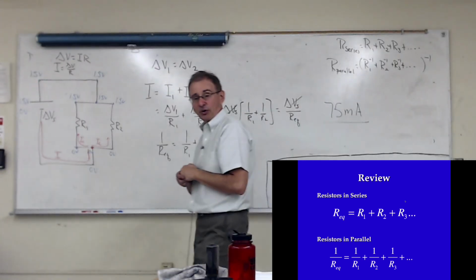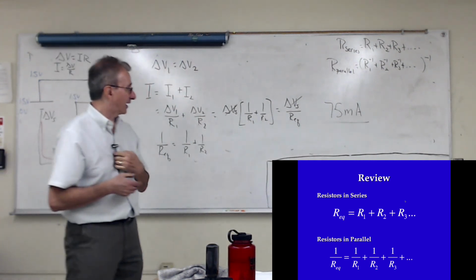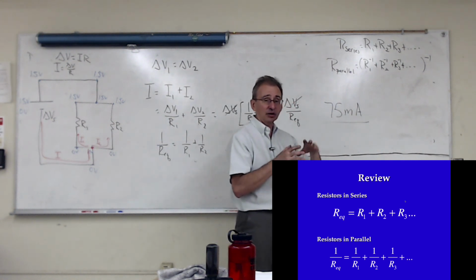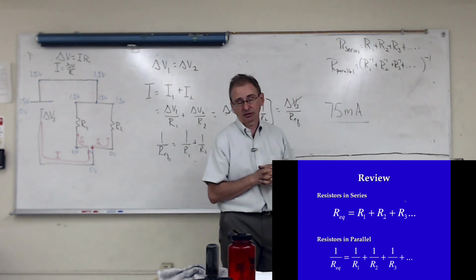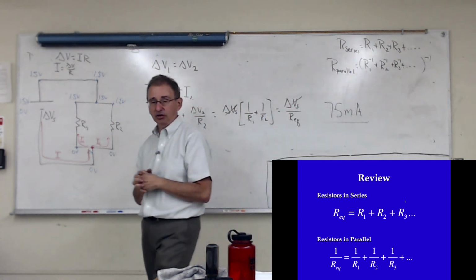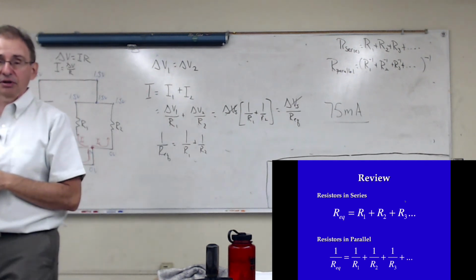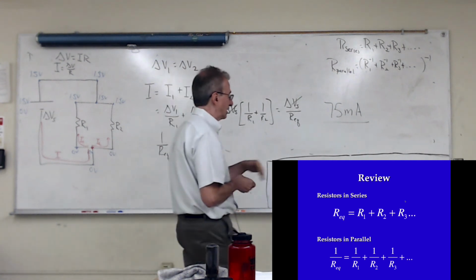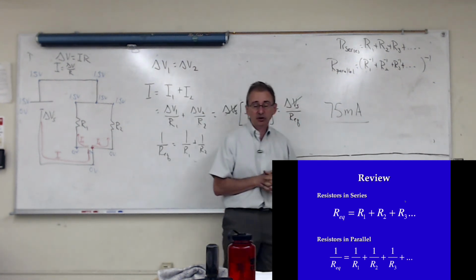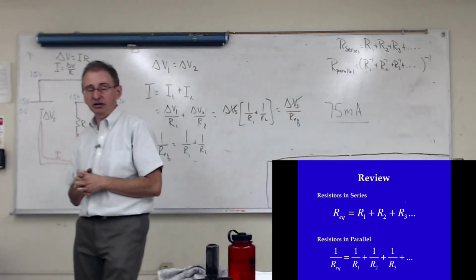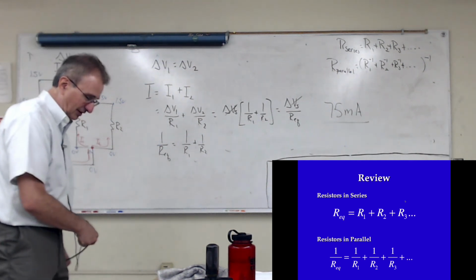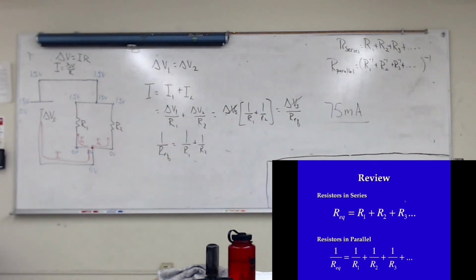You actually turn off the source. When you get to higher currents, though, like an amp, instead of going into fibrillation, your heart will stop. And if someone's able to rescue you, you can actually survive that, compared to 75 milliamps, because your heart stops instead of going out of whack. Of course, the problem is when you get to about an amp or higher, you start to cook. You'll start getting burns because that energy is converted into heat.